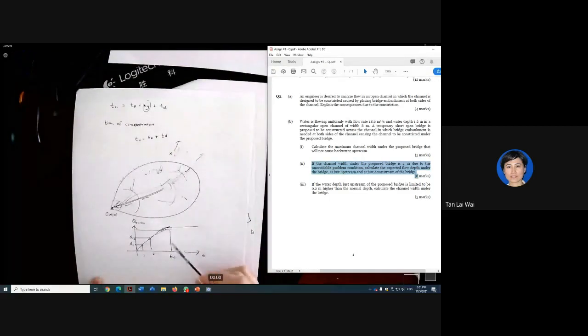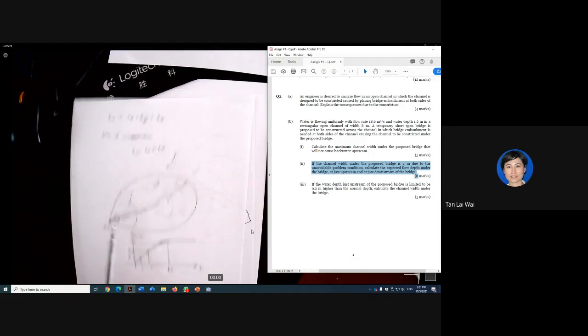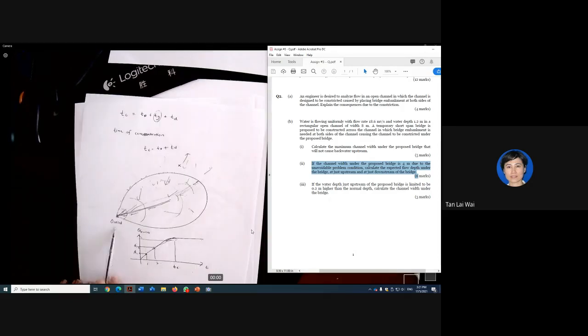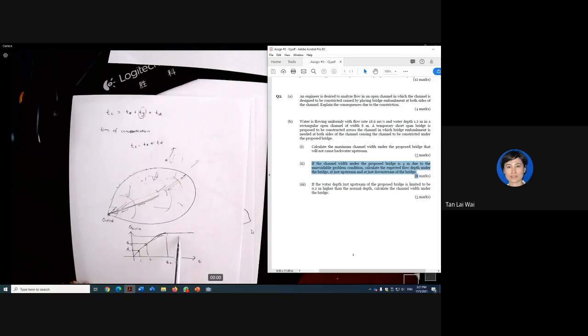When it reaches the time of concentration, all the runoff will keep coming out non-stop, and you get a constant Q already. This is when all runoff concentrates at the outlet. Just like the name, the time of concentration is the time needed for all the runoff to concentrate at the outlet. So therefore you get this here.